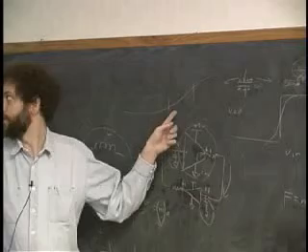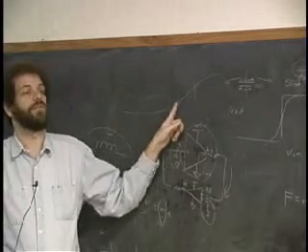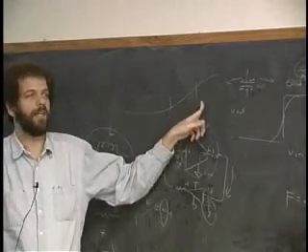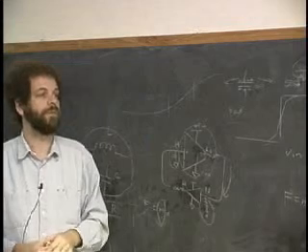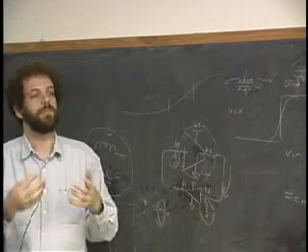But during the transition, particularly if the transition is a really slow one, during this time here, if I feed this signal into that gate, during this time, the gate will have shoot-through. Current going straight down through both of the switches from the power supply to ground. And that will dissipate some of the power.